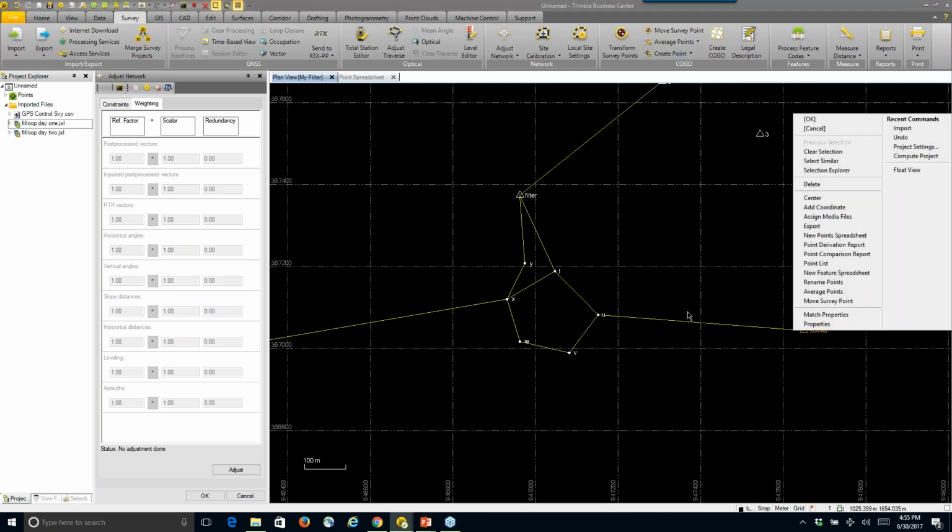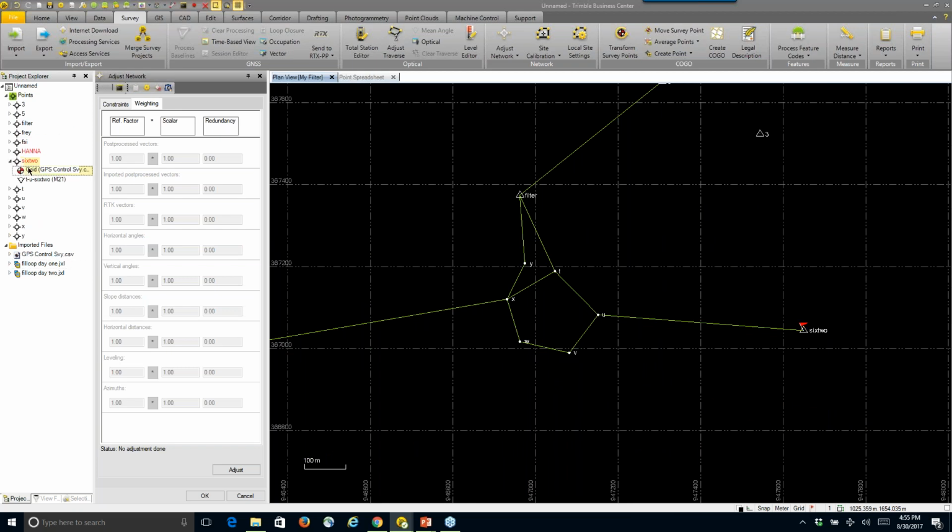Okay, so let's say that point 62 doesn't have a coordinate, and it's just whatever is computed in here. So what's going to happen is we set up here on point U, we backsighted point T, and we turned into point 62. So when you do a least square adjustment for this type of data, any adjustment between U and T is going to affect where this point is put. If it is tweaked by a couple of seconds in some way, then the new azimuth between U and T is going to be used to calculate where point 62 is going.